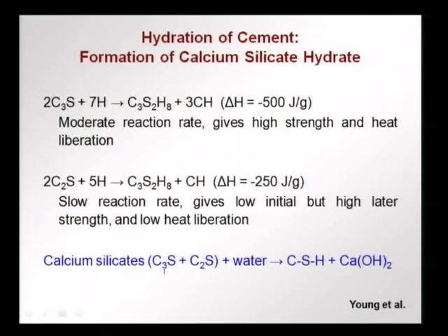Now, what happens when cement is mixed with water? The primary compound of interest is calcium silicate hydrate. This is the glue that bonds the aggregates together, that gives form to the concrete and gives concrete its strength. There are two compounds which give us calcium silicate hydrate.